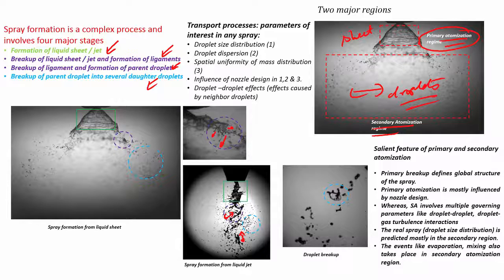And individual droplets can also break up. Due to this bag mode, this droplet can actually break up into further droplets, which will be more in the secondary atomization kind of a zone. Whatever it is, my point is very simple: the droplets actually break up, and they cannot break up without exhibiting a non-spherical kind of a shape.